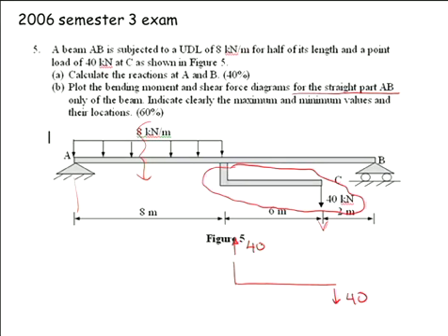And those two forces as applied, can you see they create a couple? They create clockwise rotation. So up here, you would also have a moment. And that moment, that's 6 metres. This moment here would be 40 times 6, which is 240 kilonewton metres. So far, so good? Now, they are the reactions on this part of the beam. So if I want to remove this completely from the system, I then have to apply the equal and opposite forces to my actual beam.